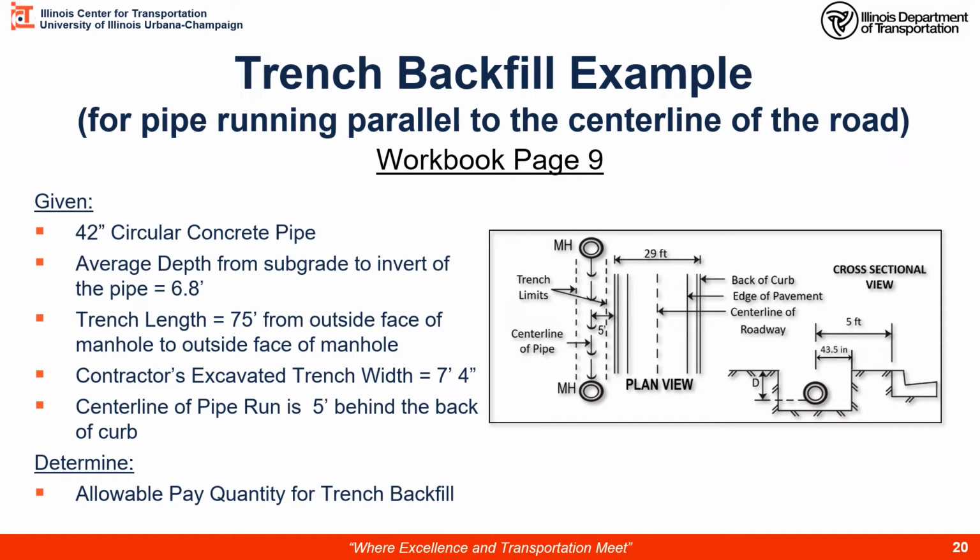In this case, we got 60 inches, which is 5 feet. And we know our center line of pipe to the edge of the trench is going to be 43.5 inches, leaving well under the 2 feet. So yes, indeed, we will pay for trench backfill from manhole to manhole in this case.